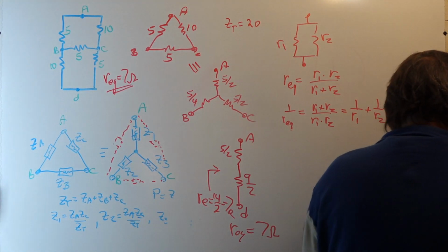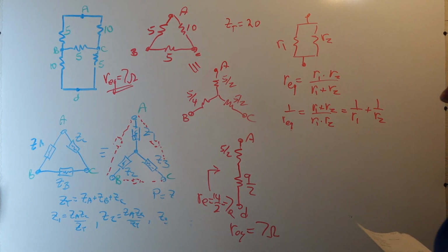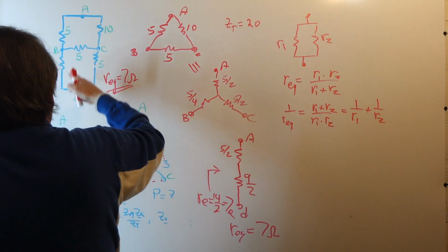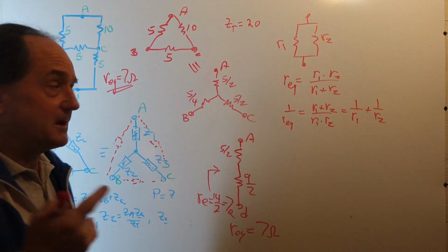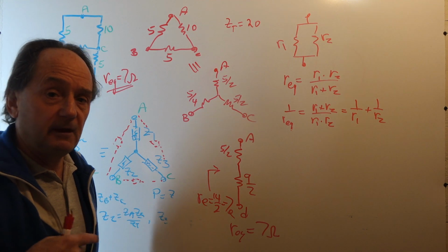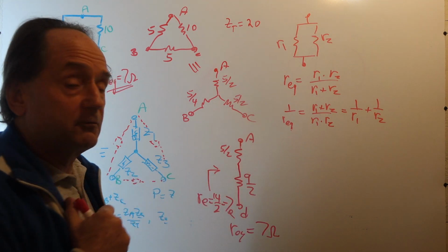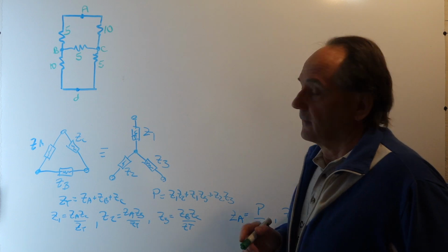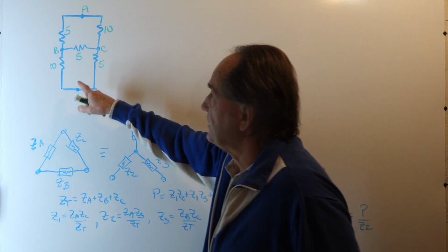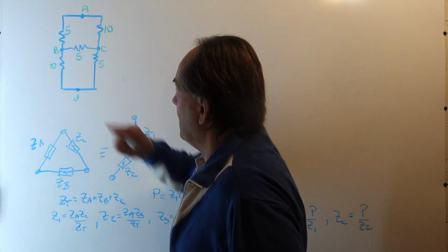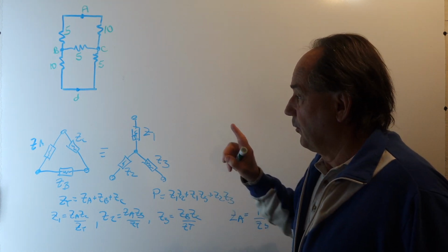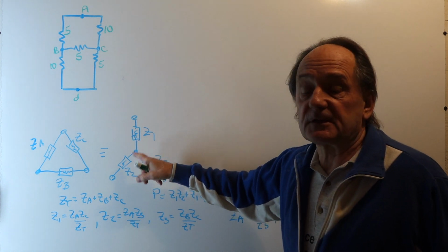Now I'm going to use the method of mesh analysis and drive the nodes A and D with a voltage source, and use mesh analysis to find the equivalent current that we need to drive into the network, and then ratio the voltage to the current to get the equivalent resistance. Now, to do a network reduction to find the equivalent resistance between points A and D, I'm going to use what's called the delta to Y conversion, or some people call the Y a star connection.